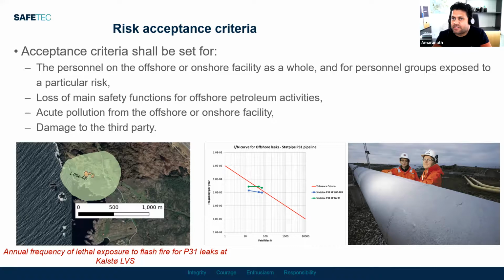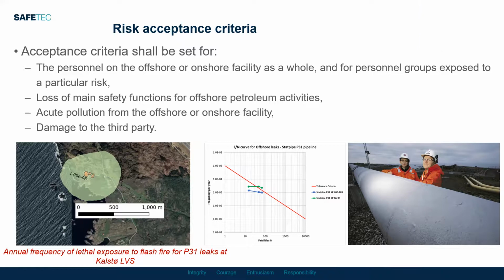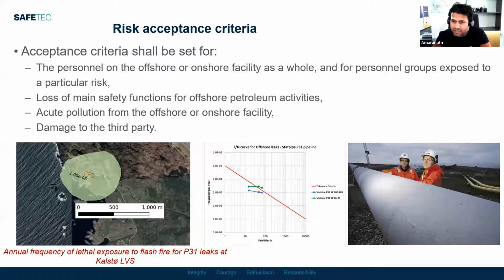If there is an accidental drop of an anchor, it can damage the pipeline. And trawling is also very important, and you have different types of trawling, like mid-water trawling and bottom-water trawling. Mid-water trawling will not influence the integrity of the pipeline, but bottom-water trawling in the area where the pipelines are located can be quite dangerous.